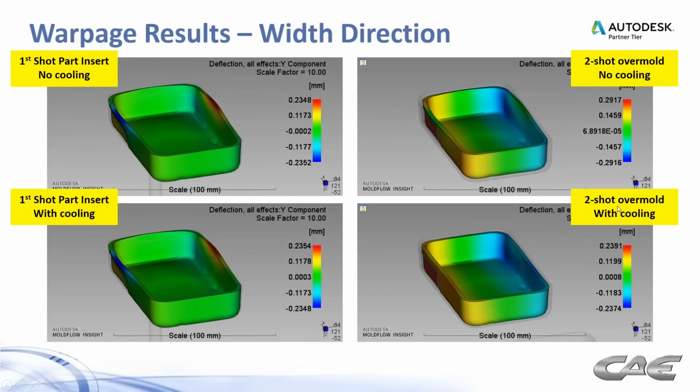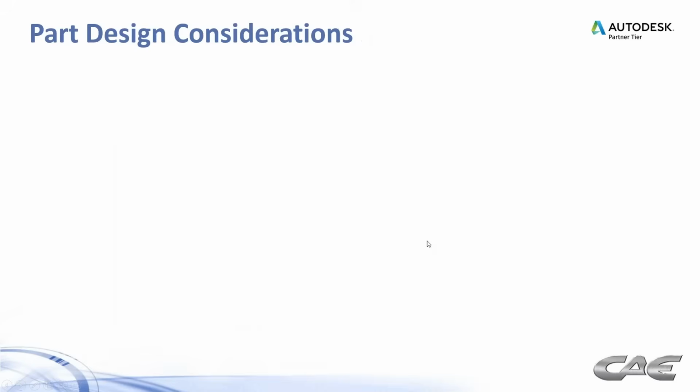So even when we add cooling to it, you can see that this outward bow goes away. And any type of box structure, when you add cooling into the analysis, typically it's going to make it bow inward a bit more. So we see that playing out where the cooling is making a difference there. And then we have the vertical direction as well.